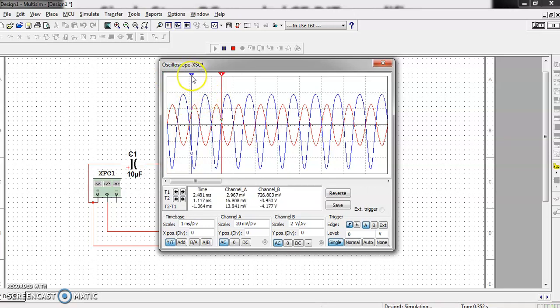See, just click on the blue color waveform and see this cursor 2 is kept at the maximum peak and this cursor 1 I have to keep at the minimum peak. Now I arrange the cursor like this. So this value T2 minus T1, this value we have to note, this value is 9.045 volt. This is our output voltage. Whereas what is the input voltage? That is 50 millivolt peak to peak, or you can say 25 millivolt peak value.